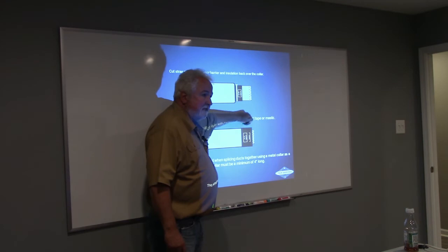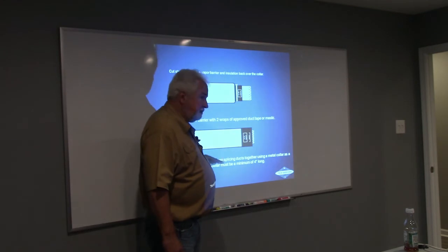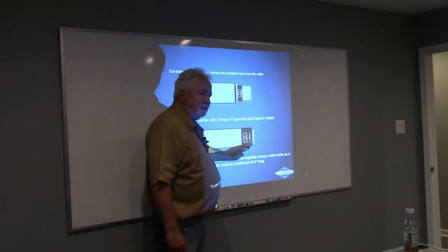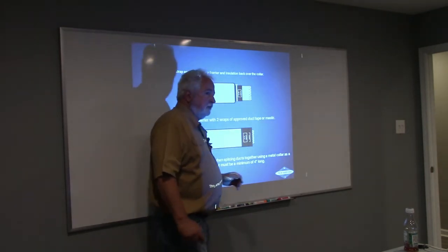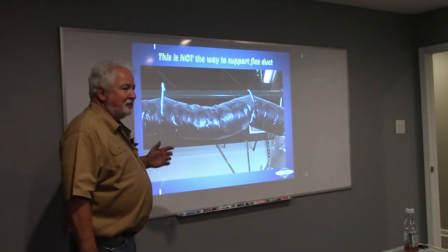I don't want any moisture from that attic to go between that insulation and that core. Because if that moisture from the attic gets in between that insulation and that core, which is going to be 55 degrees, what's going to happen to that moisture? Condensate. Then that duct is going to hang all pregged out, right? Cool. All right. Oh, like that. Not the way that we want to be running this stuff.